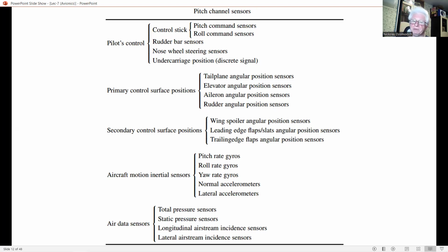Computer iteration period synchronization. The iteration periods of the individual computers need to be loosely synchronized to avoid data staleness problems. Recording of all data to enable the management of the maintenance function. System status indication to the crew and control of the overall system.